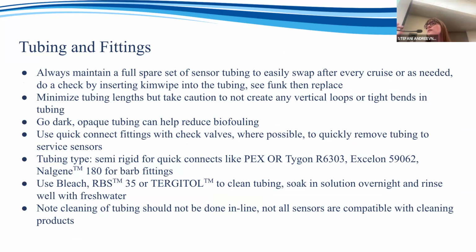Always maintain a spare set of tubing on board, right? You want to be able to easily swap tubing in and out. Whenever I go on a ship, I do a pinky inspection. Anybody do pinky inspections? You take a tube off, just rub your pinky in there and see what comes out. No, that's just me. Yeah, it's usually pretty gross.